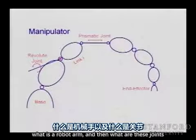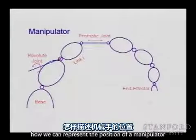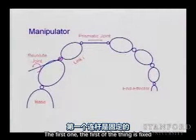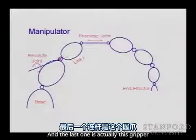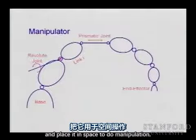And I'm going also to describe a little bit what is a manipulator, what is a robot arm, and then what are these joints, what are the degrees of freedom of a manipulator, how we count and represent the position of a manipulator. So a manipulator is defined by a set of links connected through joints. The first of those links is fixed. We call it the base. And the last one is actually this gripper.